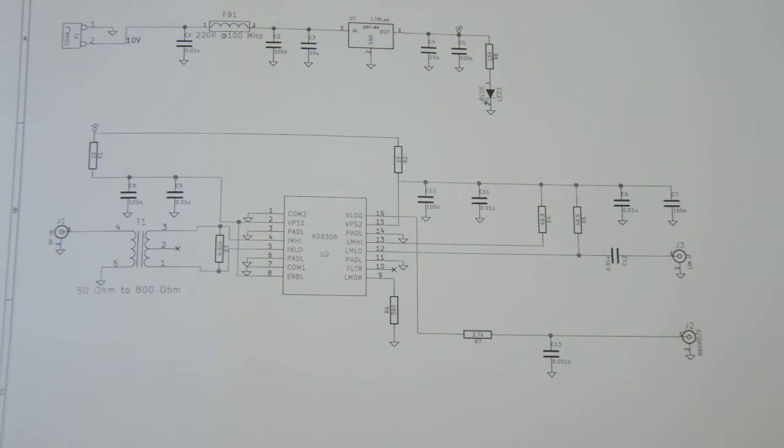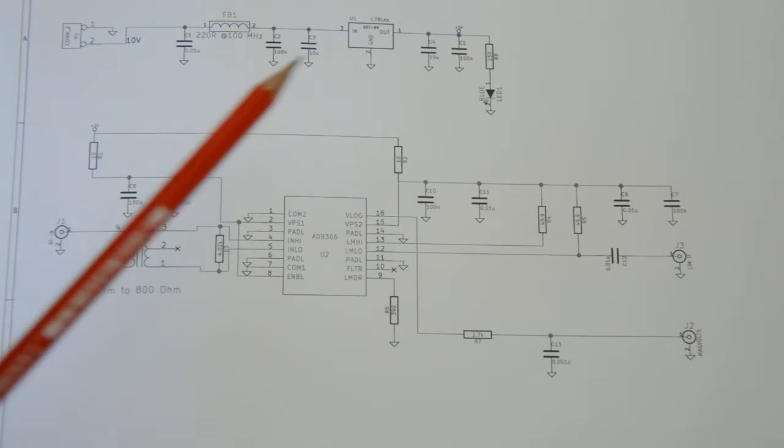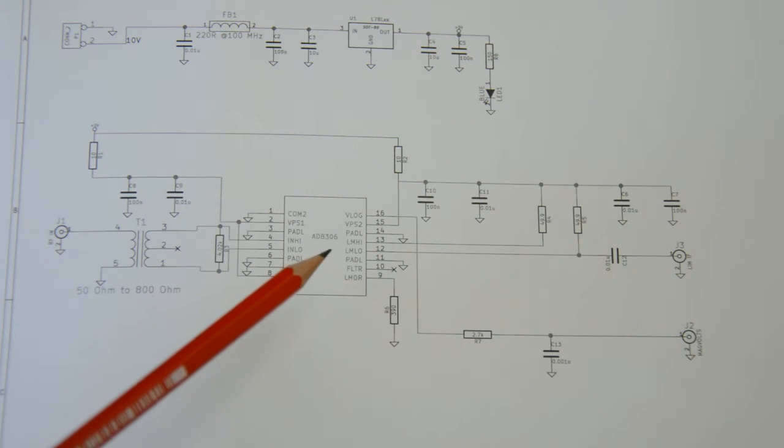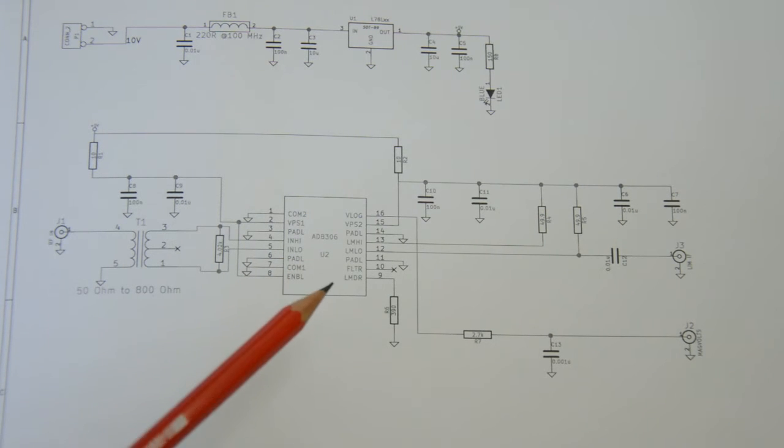This is the schematic of the log detector board. As usual, there is a local power supply section here that's 10 volts in, 5 volts out, and this section is exactly the same as it was on the other board, so there isn't anything special here. Then there is the usual noise filtering, 10 ohms plus a capacitor RC filter, that I already discussed in previous videos, but the core of this board really is this AD8306 Limiting Logarithmic Amplifier. And we're going to discuss extensively how this chip works.